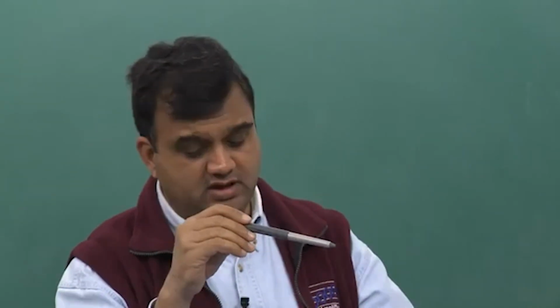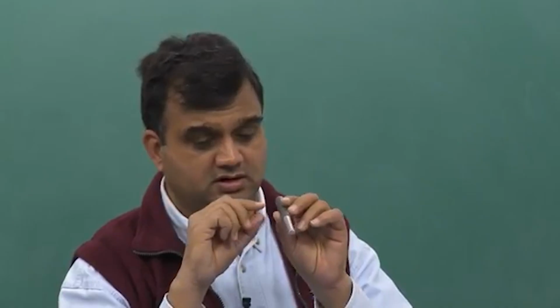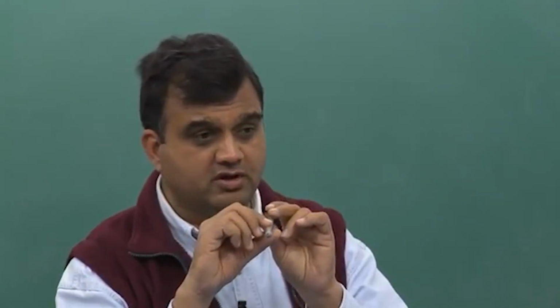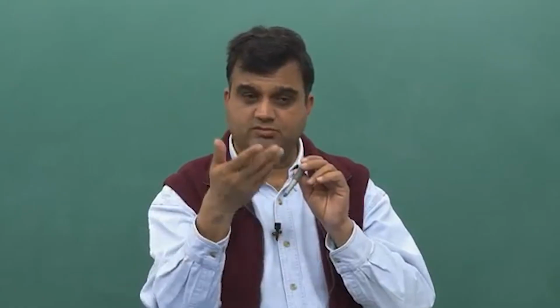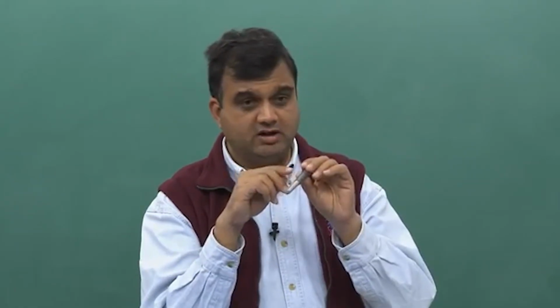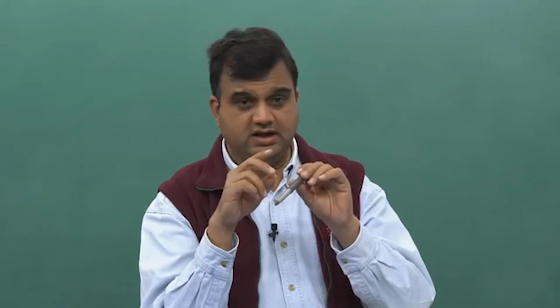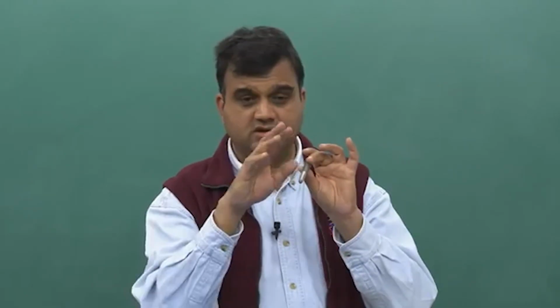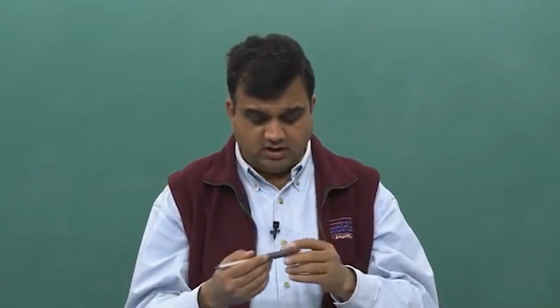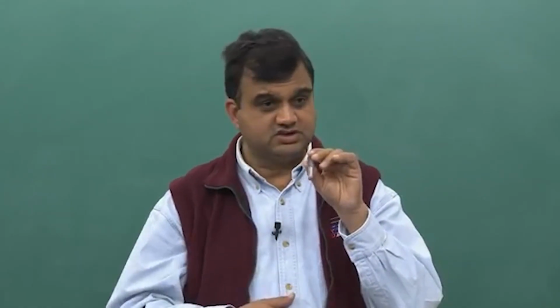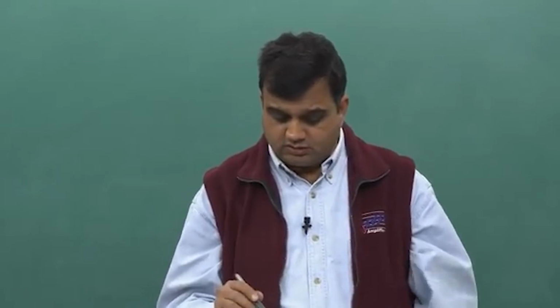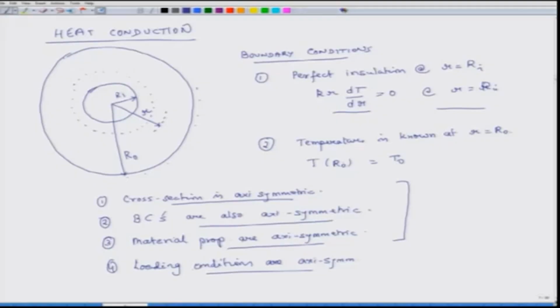The properties of the conductivity of the wire: in the center it is that of copper, outside there is one insulation, outside of that insulation there may be another layer of insulation, there may be 3 or 4 layers. So, the material properties are changing in radial direction, but they are not changing in theta direction. Also, the cross section of the wire and all individual constraints is also axisymmetric. So, everything is axisymmetric in that situation in case of wire, and same thing is here.